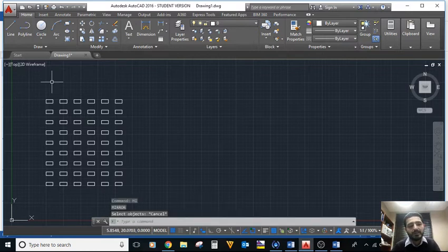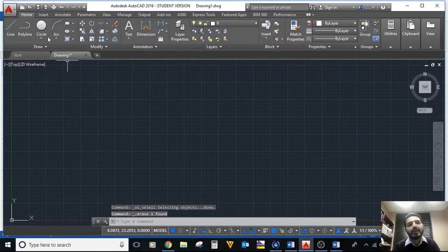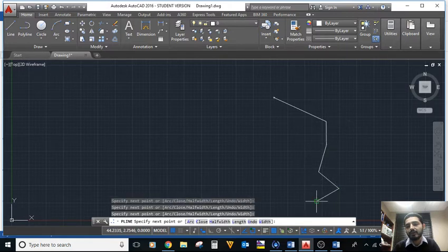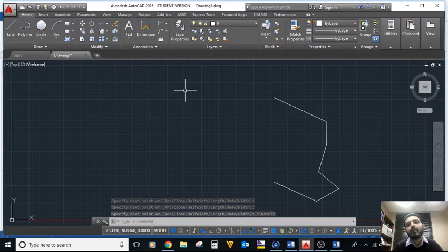So first of all, let's delete what we did, and now let's just come up with a polyline, any polyline that you want to do, assuming that you are interested in doing something symmetrical, like that. Again, any shape. Again, I'm not being specific here. Now you want, instead of drawing the same exact picture on the other side, you can mirror that.